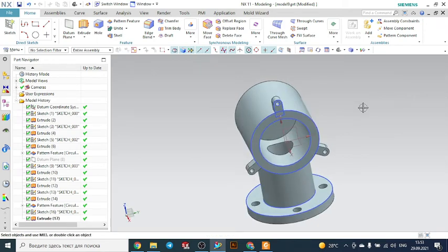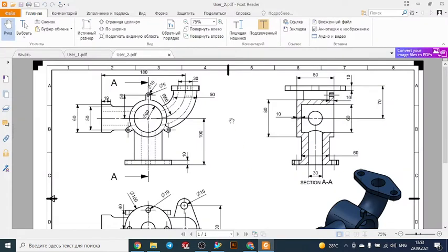Now we will go on. We can now draw this element here. Firstly, we will draw the guide curve in the middle. You see, with the radius of 60 millimeter. So here the 60 millimeter, and here we have the 30 millimeter with the straight line.